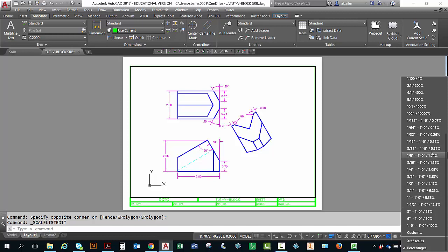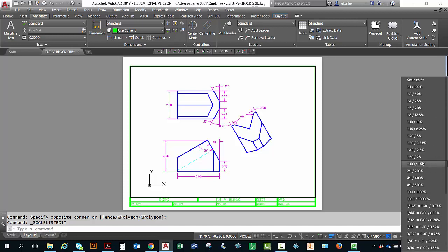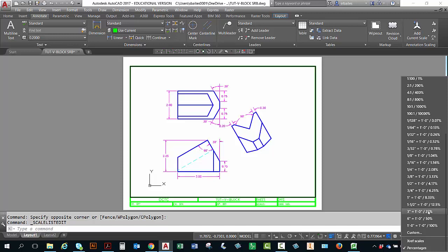So it's a great reduction, because architectural drawings are huge, and we're trying to reduce them down by a large amount. So we get on up here to 25%, 3 inches equals a foot. Here's 25%, 1 to 4. So either one of those would work if you were after a 25% scaling.